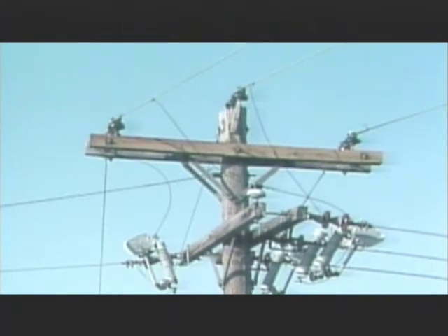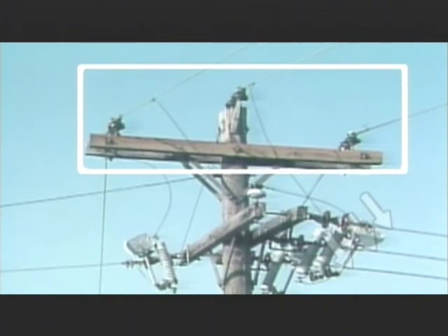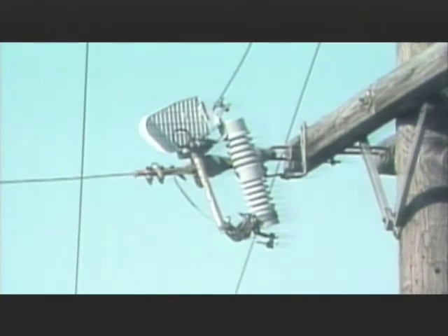However, in many systems, fuses are installed between the feeder and the laterals to provide additional protection. In this example, the feeder supplies a 3-phase lateral and a single-phase lateral. This is what a typical fuse looks like. It consists of two contacts, one tapped off a feeder and the other connected to a lateral, and a hinged fuse.